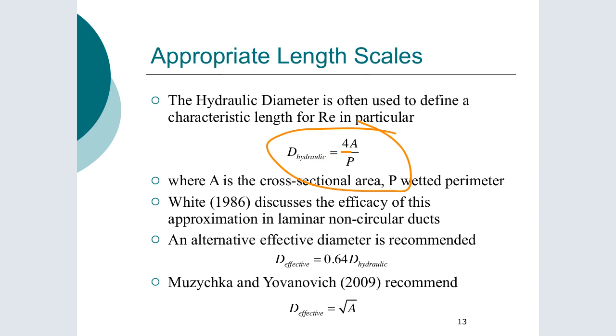And again, you can see this kind of makes sense because first of all it's tying circular stuff, which we're used to in the macro scale as pretty common geometry, with rectangular stuff, and using the cross-sectional area to the wetted perimeter, it's giving us where the pressure force is tied to the cross-sectional area, and then the shear force is linked to the wetted perimeter. So it's capturing the relevant geometry that is tied to both those two forces that are at play in fully developed flows.